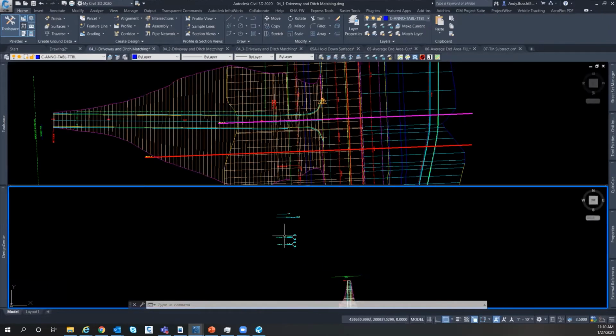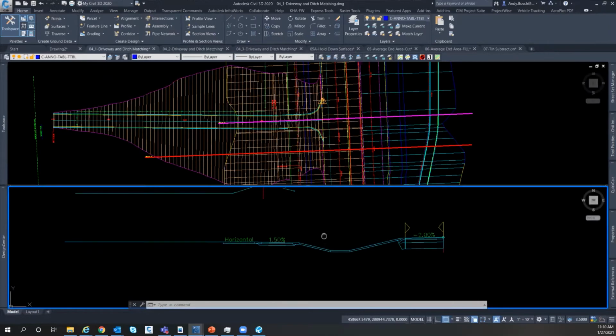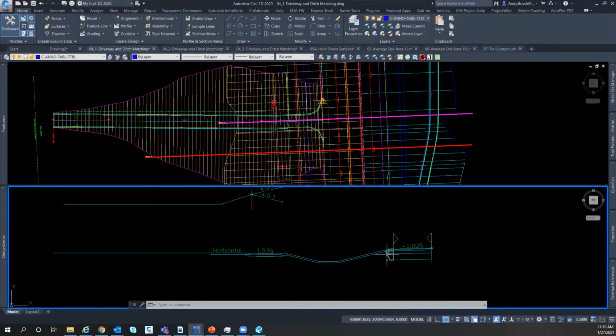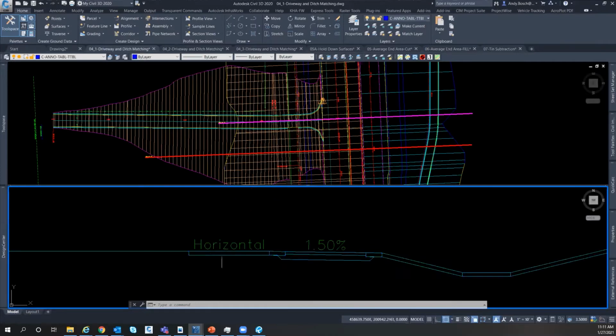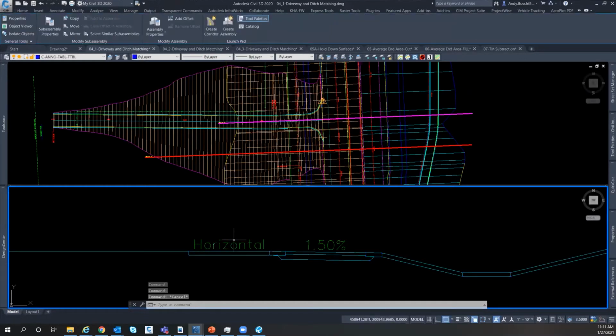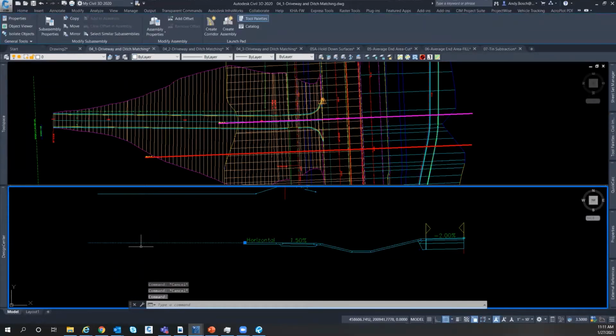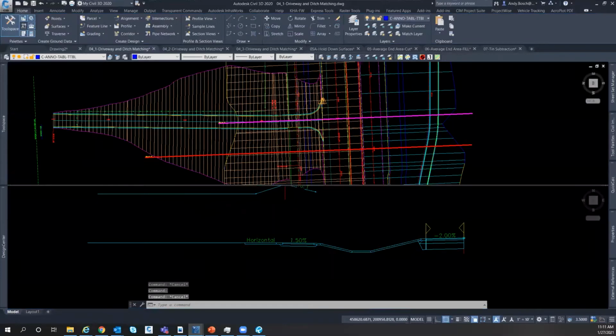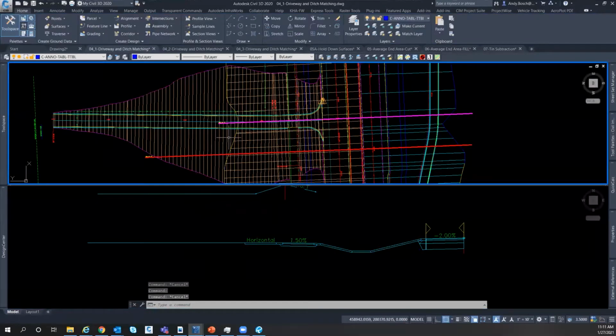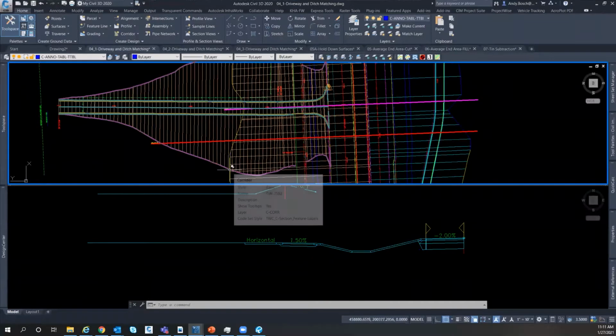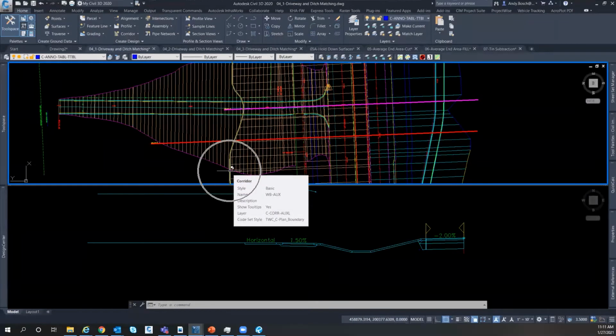And my assembly for this one is looking something like this. This is my regular roadway profile with my ditch and my trail out here, and then I'm daylighting. And if you attended the last class, you know that this is my custom subassembly that I'm using for my daylight. But you'll notice one other thing that I'm doing is I'm pushing that out another 100 feet or so. And I'm doing that just so I make sure that my surface creates all the way out where it might have to cross over. So if you look at here, at this point here that my surface has to target,